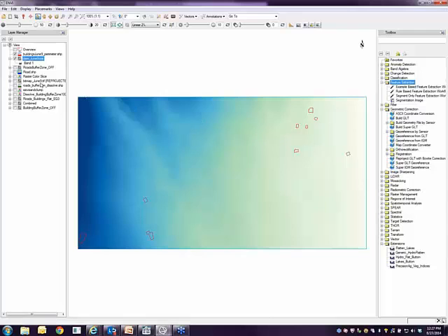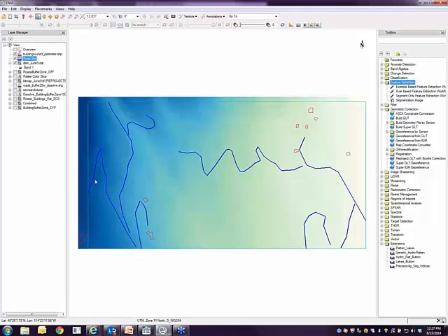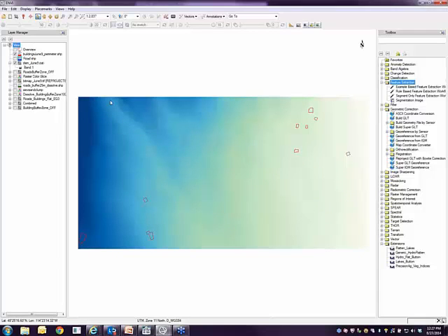We need the buffer zones around them, and we've also got some roads. So these road layers are here. So these are existing roads, and we can't be around those roads either. And these are our input products. So one of the first things that I did was I decided, okay, I need to have these buffer zones around my roads and my buildings. So using ArcGIS, just a click of the button, let's create these buffer zones around the roads and around the buildings.